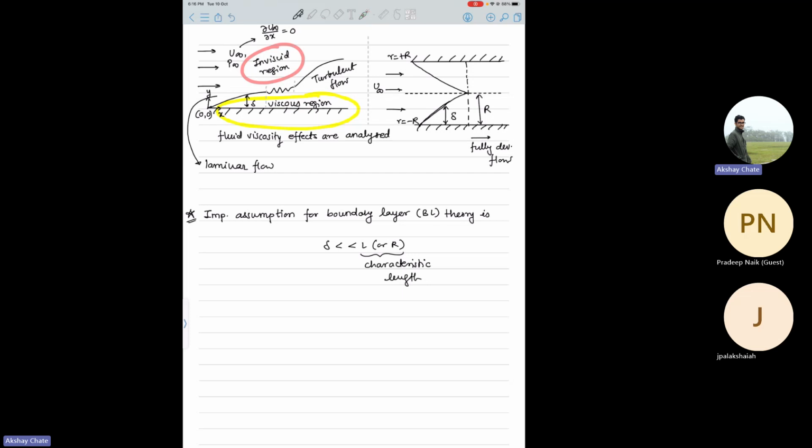So basically, earlier we were doing some calculations, right, where you get a parabolic profile in this region like this. So then that becomes that similar problem that we solved earlier, where you get parabolic velocity with some mean velocity, with maximum being twice the average, like that. Okay. In the developing region, what happens? I mean, in general, the fluid in the boundary layer is a retarded fluid because of the viscous effects. So in general, yeah, thank you for asking this question. I forgot to mention one point. Typically what happens in this region, you will have a flow of fluid, and in this region also you will have some fluid flowing. But what happens in the boundary layer, the fluid velocity gets reduced because of the viscous effects.